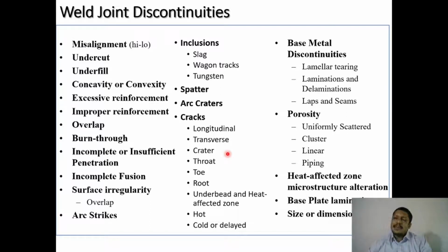Mostly the acceptability will depend on where that material or product is going to be used. Depending on usage, certain flaws or discontinuities we can say are defects, and they need to be rejected. If a discontinuity is seen in a weld, you have to repair the weld.